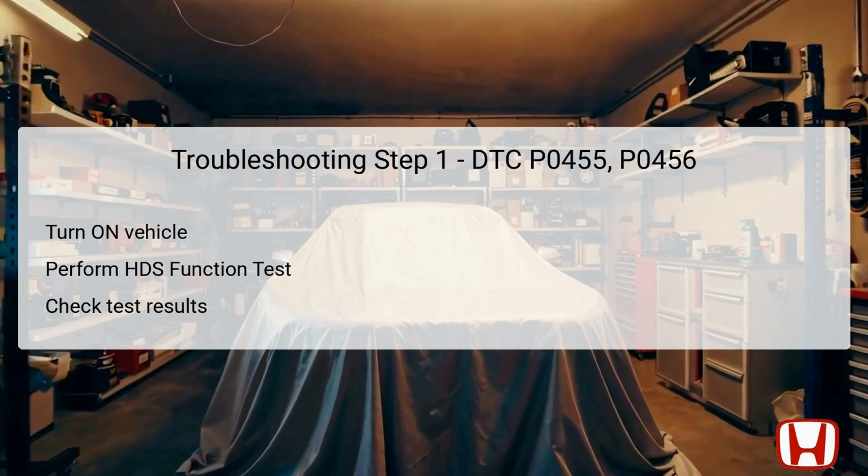Begin troubleshooting by ensuring that the vehicle is in the on mode without starting the engine. Utilize the Honda Diagnostic System, HDS, to conduct a function test with emphasis on the EVAP system. This diagnostic procedure will assess the functionality of various components and provide immediate feedback on their operational status. If the HDS indicates that the results are not okay, it signals that the identified failure needs to be duplicated for further inspection. This first step is essential in isolating the specific part of the EVAP system that is malfunctioning.